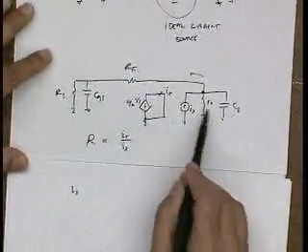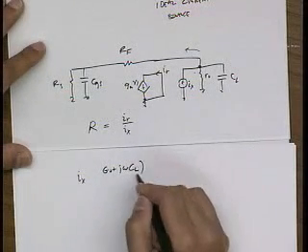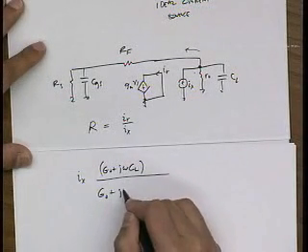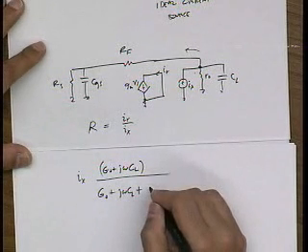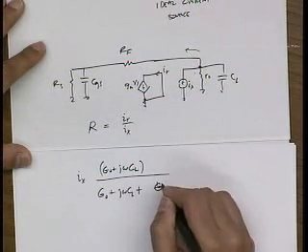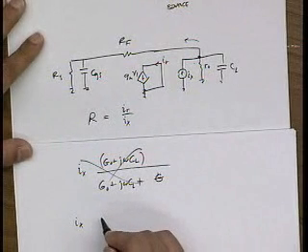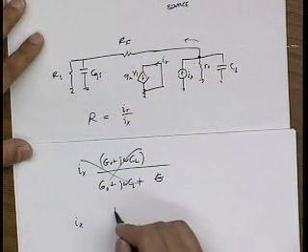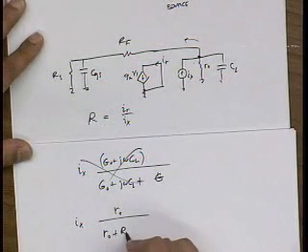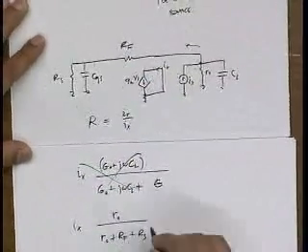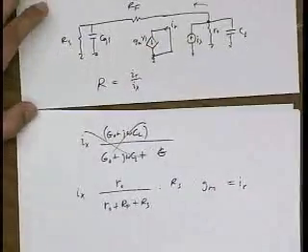So that would be this impedance, let's say G0 plus j omega CL, divided by G0 plus j omega CL plus now 1 over, let's say, yeah, it's getting complicated. Let's do it at low frequency so it's simple. I'll let you guys do the high frequency version at home. So then it's just RO divided by RO plus RF plus RS, times RS times GM. That's my return signal.